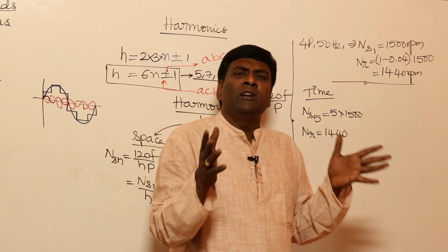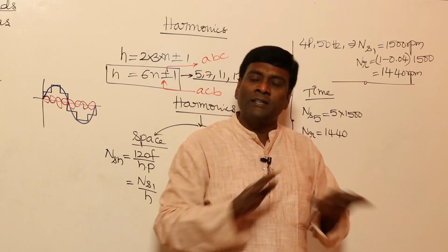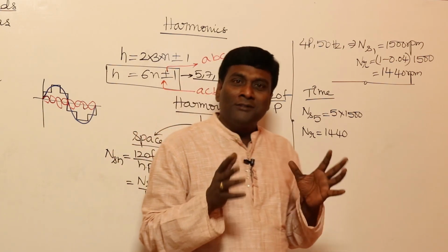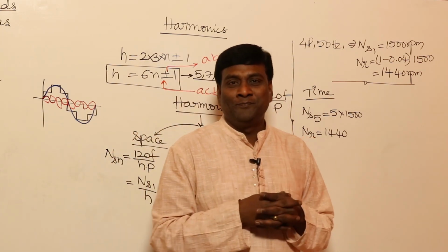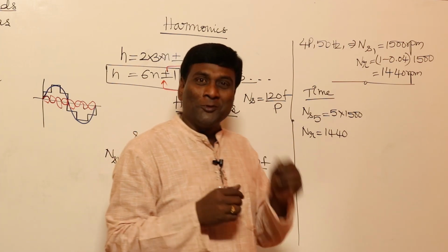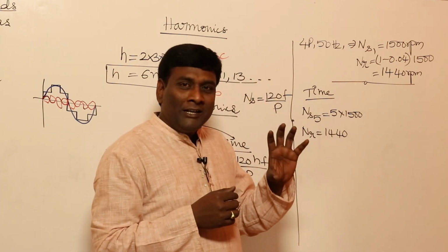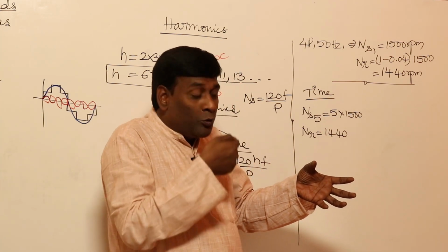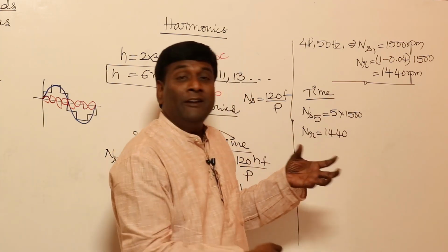Actually they may give you different formulas and all. Formulas are not at all required. If you see my class notes, you might find formulas. Don't remember that; sometimes we have to do that as faculties, just to scare people. Now, if the rotor is rotating in this direction with 1440, my stator MMF is rotating in the opposite direction with 5 into 1500.